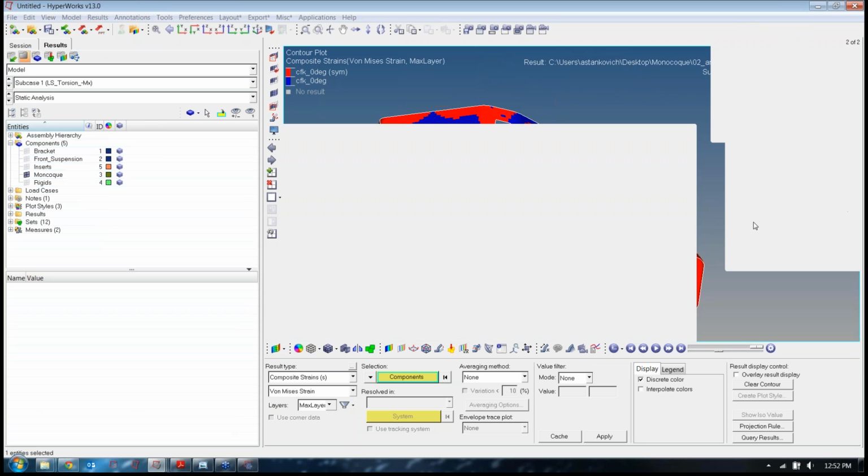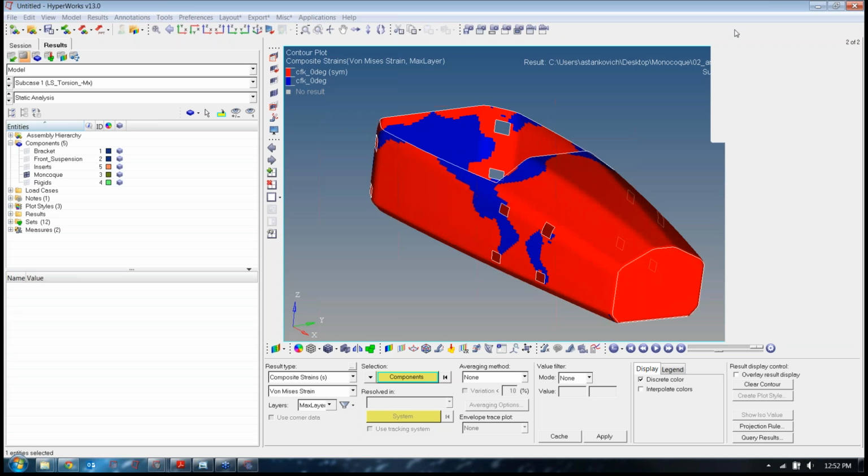Good. The next question is, is the composite optimization process based on the density method, such as for topology optimization? We are not doing a topology optimization. We're doing a free size optimization. The design variable that it's looking at in the math is the physical thickness of each element. It's going into the property card, into the ply card, excuse me, and varying that thickness on a per element basis and going through it that way and finding the ideal. So it's not density based, it's actually thickness based. It's working on the properties.